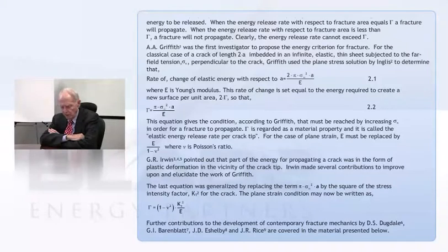So he showed for a crack, there's an expression here, for gamma is 1 minus nu squared, this K1 squared over E. Now, K1 squared comes strictly out of an elasticity solution. And that's the good news, because we can solve elasticity problems. We can evaluate in terms of the load what the K1 would be, and that would give us a means of measuring K1 and thus capital gamma.